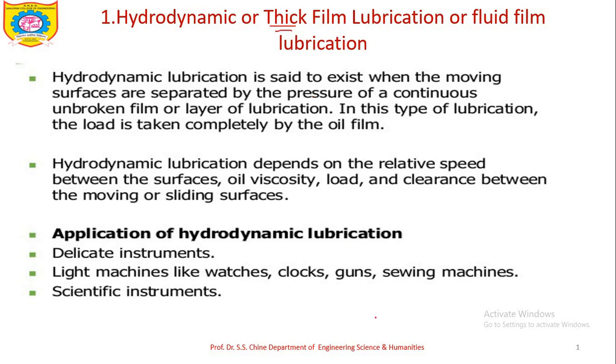Then this hydrodynamic lubrication depends on the relative speed between the surfaces, oil viscosity, load and clearance between the moving or sliding surfaces. Then applications of this hydrodynamic lubrication. The well-known application that all of you know is clocks. Our watches. We are using wristwatches or clocks. In that there is use of this hydrodynamic or thick film lubrication.